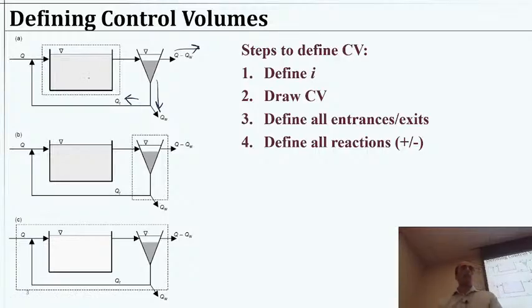It turns out this is also a way we can do some coagulation and sedimentation. If we have some, and I think we have an example from the book in a moment, we could have some precipitation occurring in here to remove some dissolved solids and then letting those solids settle. And sometimes we might even recycle some of those in order to act as seeds for other precipitates to have an easier time beginning the precipitation process. So it turns out this is a pretty common schematic in water treatment where we have a sedimentation chamber. This allows us to separate solids from the liquids just using gravity. We're going to take a deeper dive into that later.